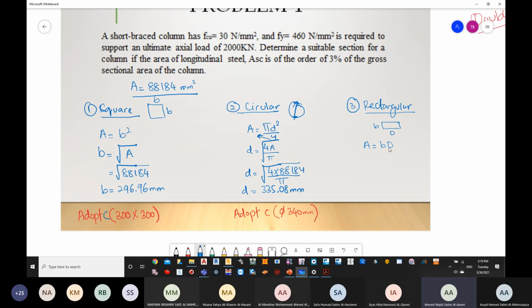Okay, if your width is more than 200, then you will see that your column is going outside the wall, because the width of the block is 200, which means the width of the wall is 200. So to sort out this thing, normally we keep our width the same as the width of the wall.